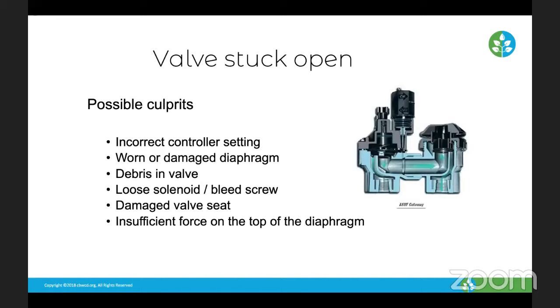So let's say the valve is stuck open. That means it's constantly running. It's not closing when it's supposed to, and we're not sending any power to the solenoid telling it to open. It's just constantly leaking. This could be partial leaking, where the valve's not completely open but it's seeping water into our system, or there's an obstruction and water is continuously flowing.